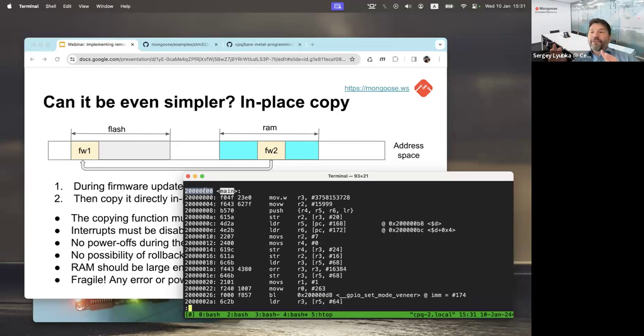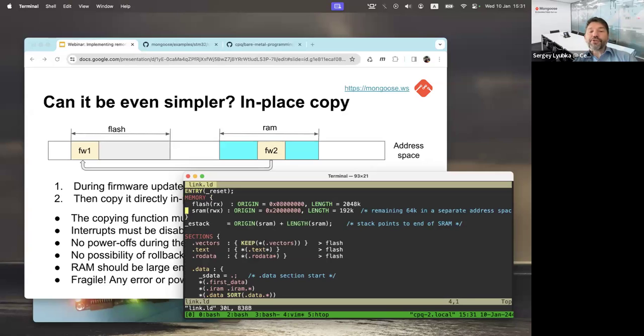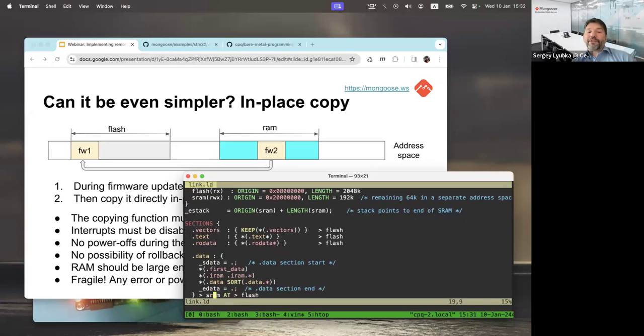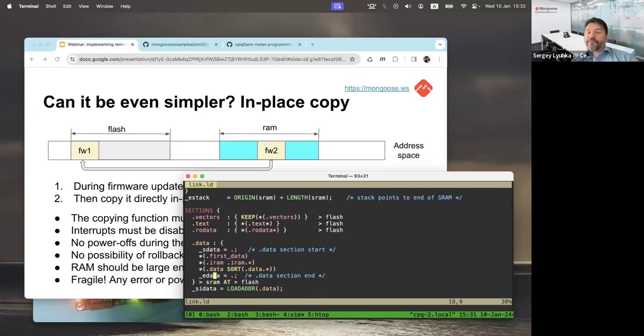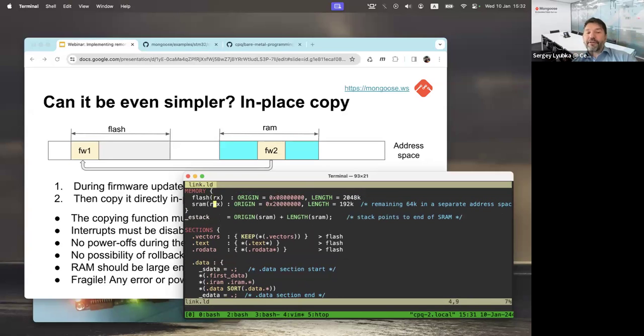Usually people put variables into a specific section because, if your microcontroller has different memory regions starting from different origins, you can specify in the linker script a specific section name and route that section name into a given memory region. That's what people use the trick for with data. But for functions, you basically select any name and put that name into the data section here.